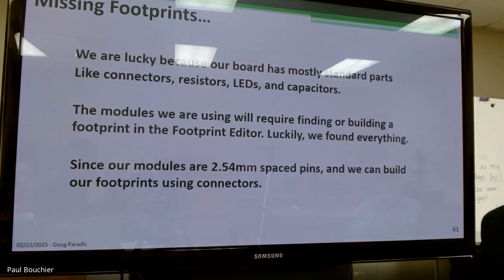we're lucky because our parts are mostly standard parts, like connectors, resistors, LEDs, and capacitors. The modules we are using will require finding or building a footprint. But I will tell you that the internet is your friend. You can almost find a footprint for everything. Now, is the footprint good? It's sort of like if you're a 3D printer and you go out to Instructables, there's a lot of files out there. And when you find a good one, it's really golden. But for every good one you find, there's some real dogs.